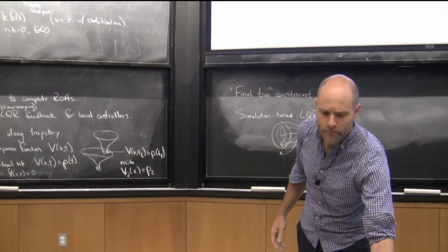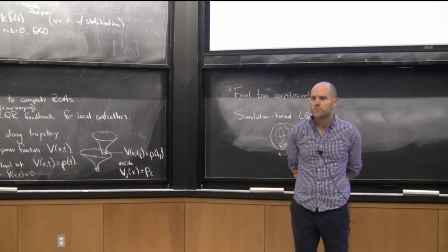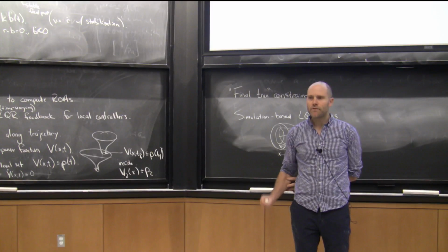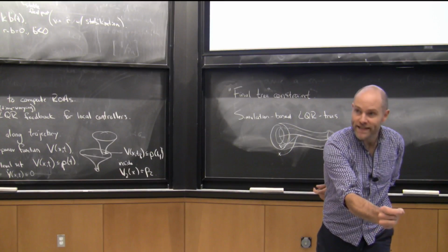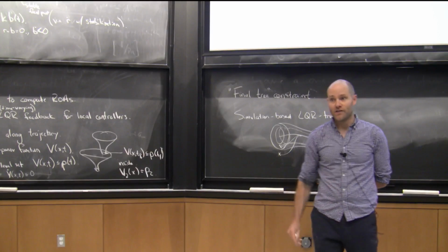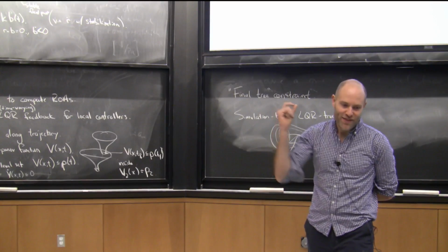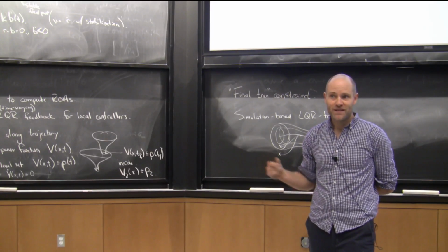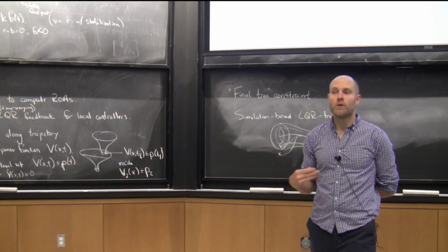Yeah. What if you had a model for your perception errors, then could you still use this? Because then it's similar in concept to having uncertainty in your obstacle errors. So that's exactly what I tried to say. If the error of my perception system is that I always identify that cup, but I identify its pose plus or minus 3 centimeters, that I can handle. If it's that I didn't even see the cup, or I thought I saw a cup, but it actually wasn't a cup, which is the way real vision systems work, then I've got nothing. I think certificates are possible, but we don't have them yet, right?